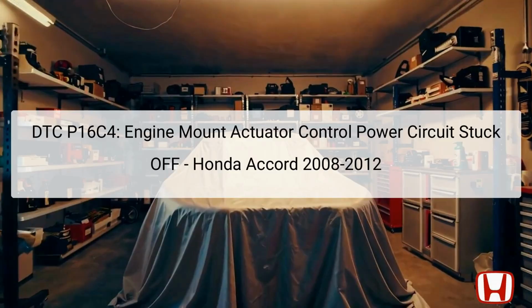The Diagnostic Trouble Code, DTC P16C4, indicates an issue with the engine mount actuator. This specific trouble code points to the power circuit being stuck off, thereby affecting the vehicle's ability to effectively manage engine vibrations. The engine mount actuator plays a crucial role by controlling the position of the engine mount, ensuring smoother driving experiences by reducing vibrations felt in the cabin.